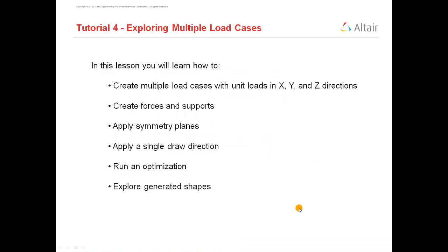In today's session I am going to discuss tutorial 4, exploring multiple load cases. In this lesson we are going to see how to create multiple load cases with unit load in XYZ direction, then create forces and supports, apply symmetric planes, and apply a split draw direction, not a single draw direction. Then we run an optimization and explore the generated shapes.